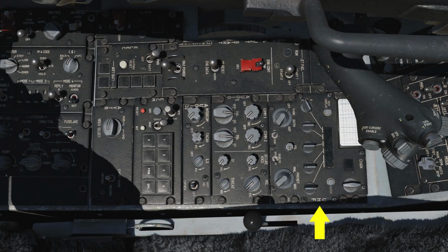While most of your radio use will be through the Integrated Control Panel, or ICP, and the Data Entry Display, or DED, on the instrument panel, a backup UHF radio head is also available and must be used before engine start, as it's the sole radio that functions only on battery power. For those familiar with our 810C, this is the exact same UHF radio. This includes a door with a preset channel entry button behind it with the selected preset channel to the right of the door. To the right of that is a knob that selects the preset channel.